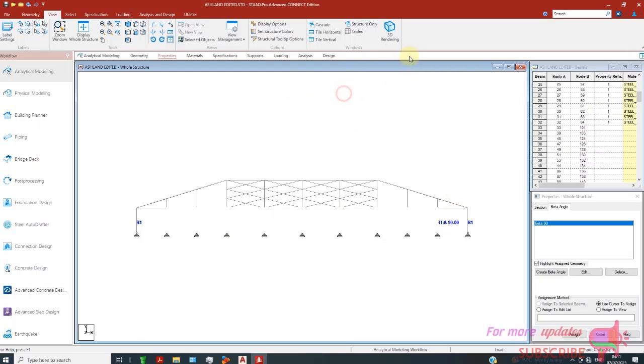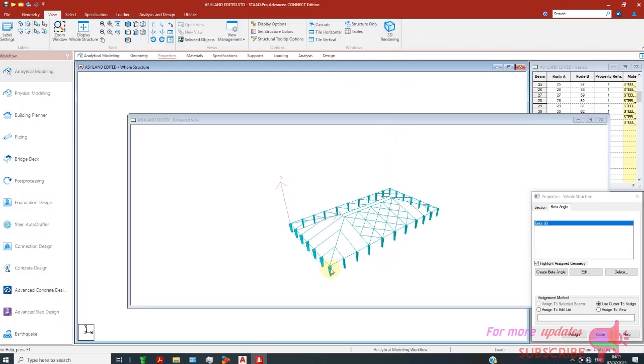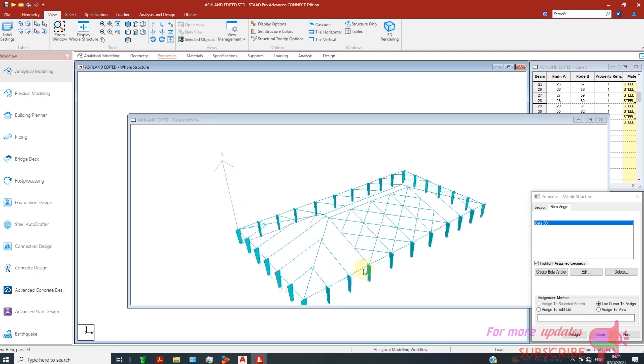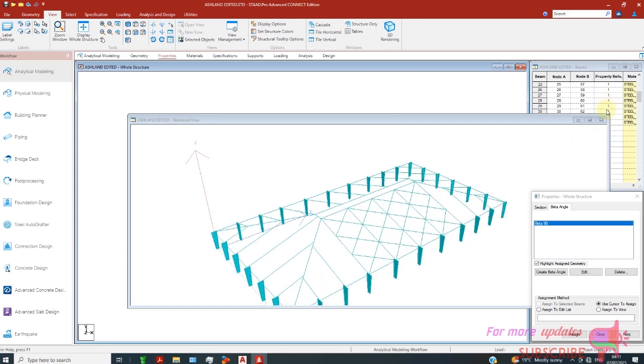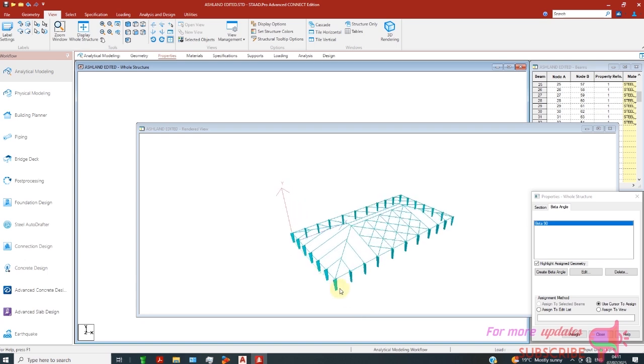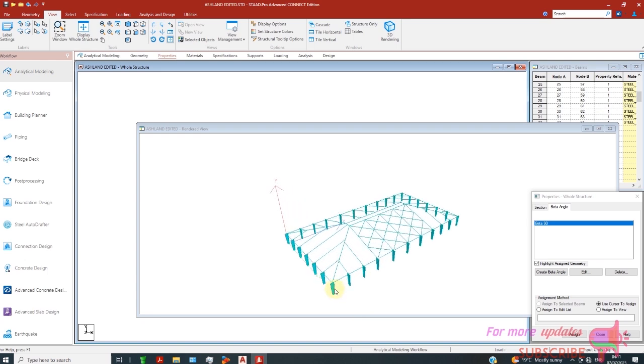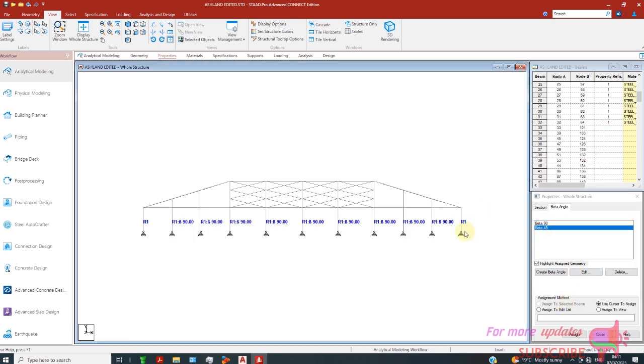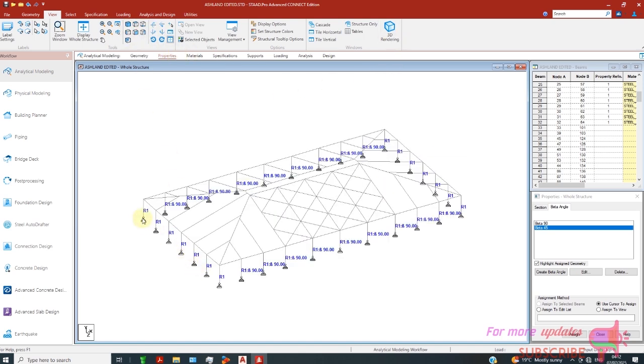If I now go to everything, you can see. Now the other problem is, if you notice, this one I want to rotate by 45 at the corners. So I will create a new angle, 45. Okay. Then we can just go to that view, pick, right click.